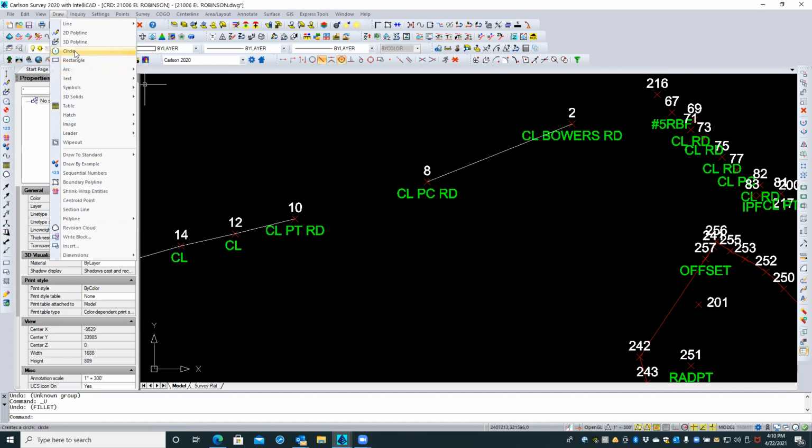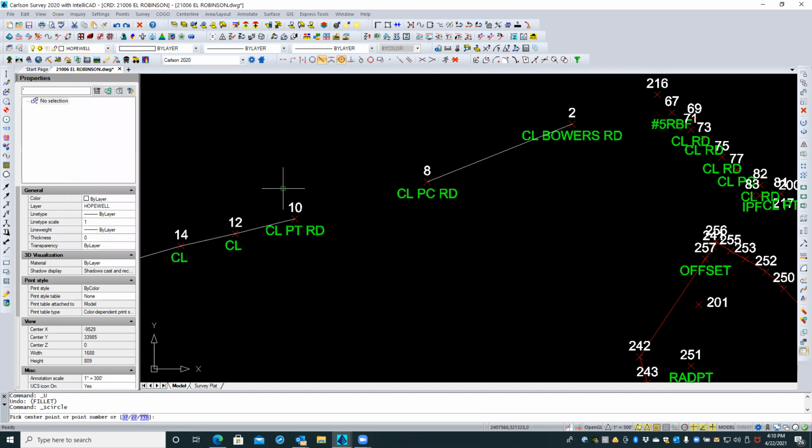All right, so if we draw a circle then instead, I've got three options to draw a circle. I can show 3 points and it will draw a circle that goes through those 3 points. Now that's no tangent guarantee, it just goes through those 3 points. 2-point circle, of course, you define a chord along that circle and then you have to supply the radius. But tangent radius, oh shoot, this is still going to require a radius value. All right, let's fix this up.